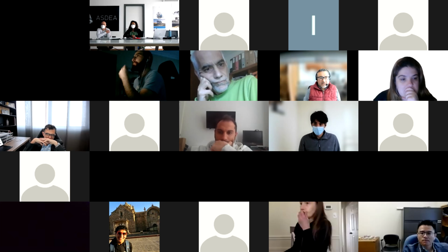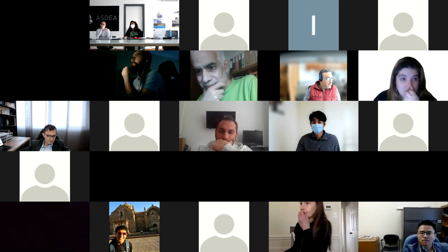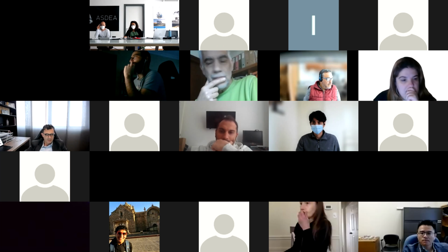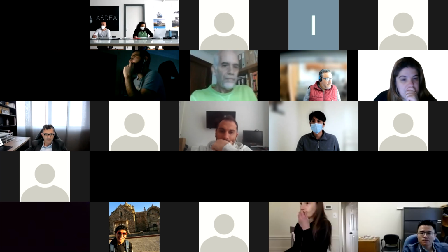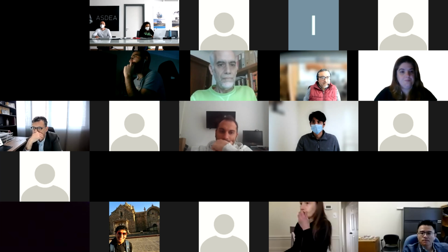We have another question. I suggest for STKO, it would be useful if we had keyboard shortcuts for commands which are most often employed. For example, fit-all can have the shortcut. There are some of them, yes. Another thing that you can do is to use the command name in the terminal window, because every command has a name. So instead of clicking on the button, you can directly type the name. Not all of them have a shortcut, because actually there are so many commands that not all of them can have a shortcut. But with time, yes, we will consider this.